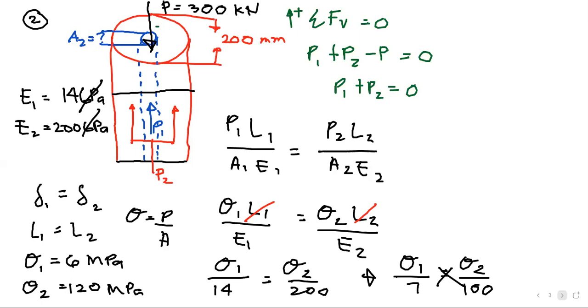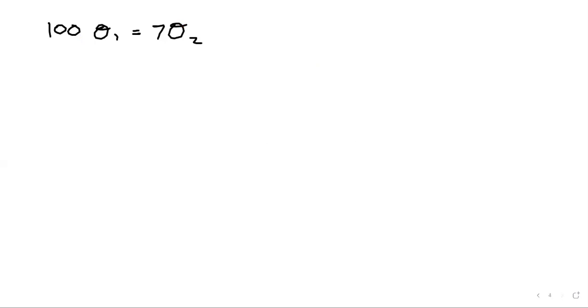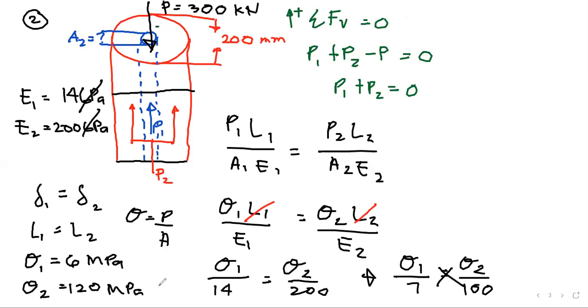Technically, guys, ang purpose ng allowable stress, ibig sabihin, up to that point lang yung stress natin. So technically, example, allowable stress for concrete is 6 megapascal. So once na sumobra ng 6 megapascal yung stress natin for concrete, ano ibig sabihin? Once greater than 6 megapascal, we can say that concrete fails. Okay? Diba? So, ibig sabihin, nag-fail na yung concrete natin.